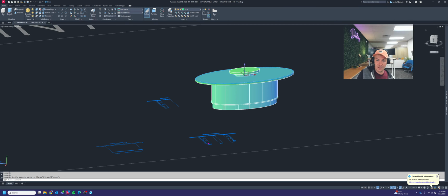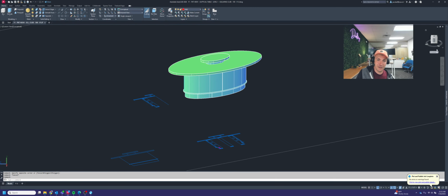All right, plotting mode for something like this. So you see my view cube's messed up too. Sometimes that'll happen if you're working in 3D. If your view cube is flipped over on its side, like it's facing the wrong direction, go down to this little drop down here where it says unnamed, and then you're going to hit WCS, which stands for World Coordinate System, which is the standard XY top-down view for AutoCAD.